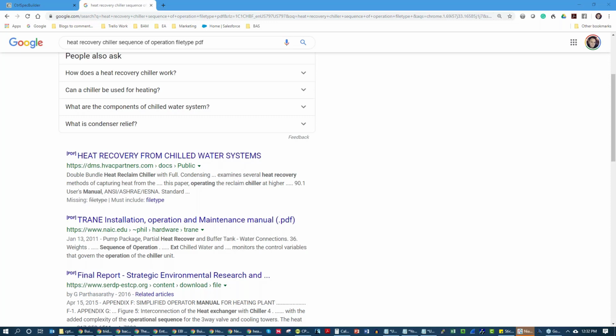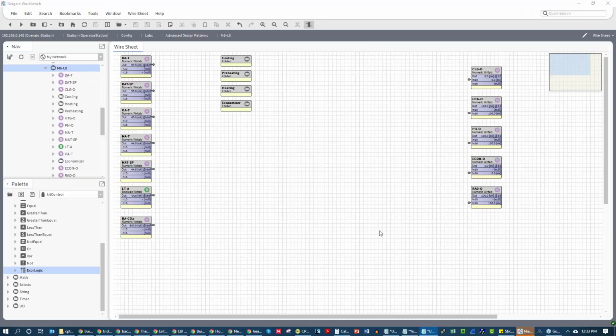Because a vertical stack heat pump essentially is a device with a compressor built in, with a reversing valve that can reverse the flow of refrigerant to not just remove heat from the building, but also add heat to the airstream. Excuse me. And that's something we talk about in our control sequence course.